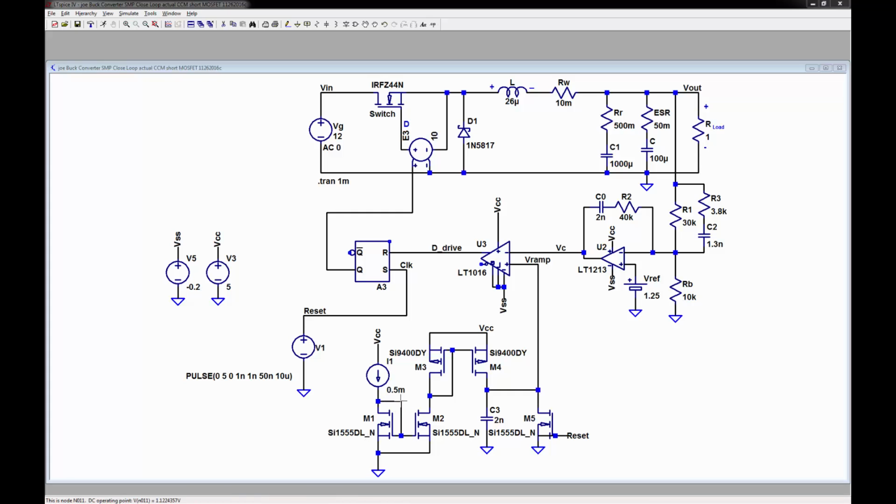So there's no current that goes into the gates. So the current goes into the drain, which sets up a VGS here. Well, these are identical. So that VGS will set a VGS. And what determines the current? VGS. So this current will be equal to that current. And that current right now is set at 0.5 milliamps, 500 microamps.